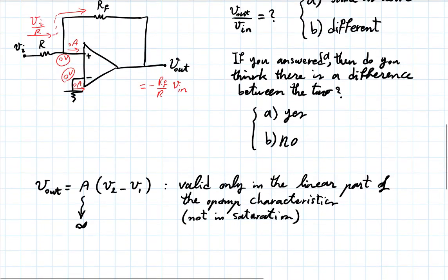So the assumption that perhaps I should question, not just in this circuit, but in any circuit, is whether the op-amp is operating in the linear region. And this is something that in the examples we've seen so far, I've kept saying, assume that the circuit is built such that the op-amp is within its linear region. Okay? But why should you accept that assumption? What I'd like to think about a little bit here is what makes it stay in that linear region.